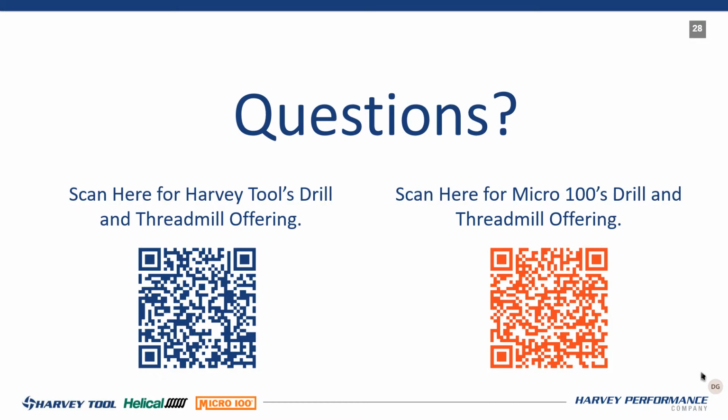But I'm going to tell you, if your drills are breaking, it's because of the chip management and the pecking, if it's not cooling through. And we can fix that. Give me a call. We'll fix it.